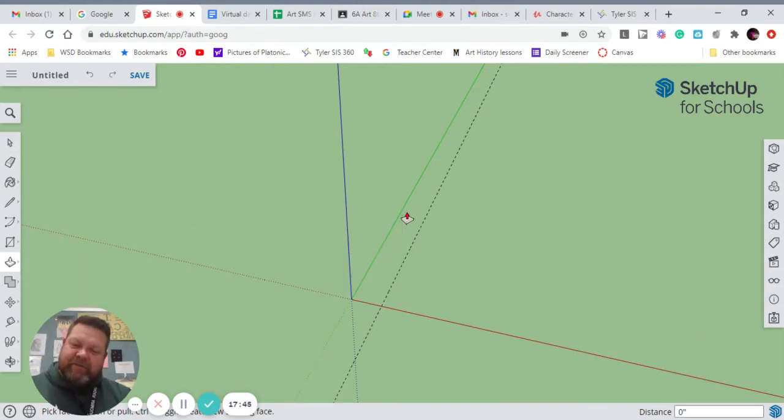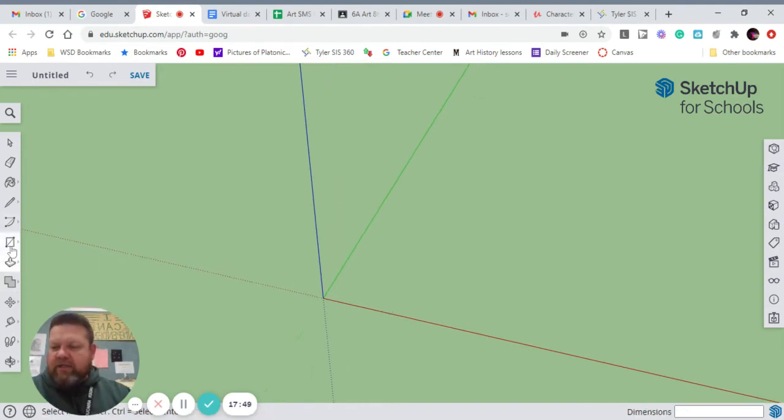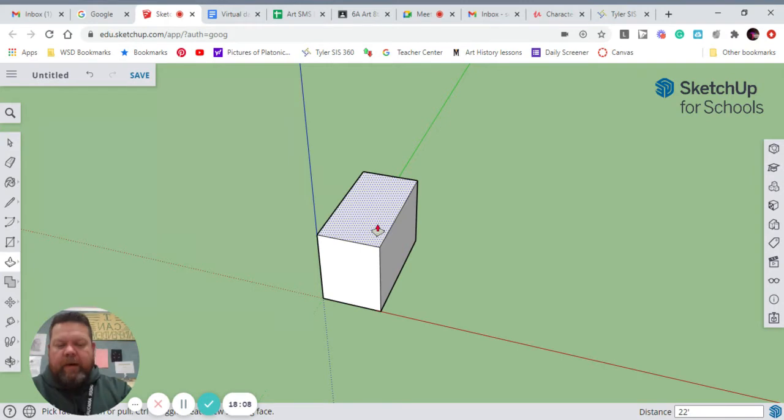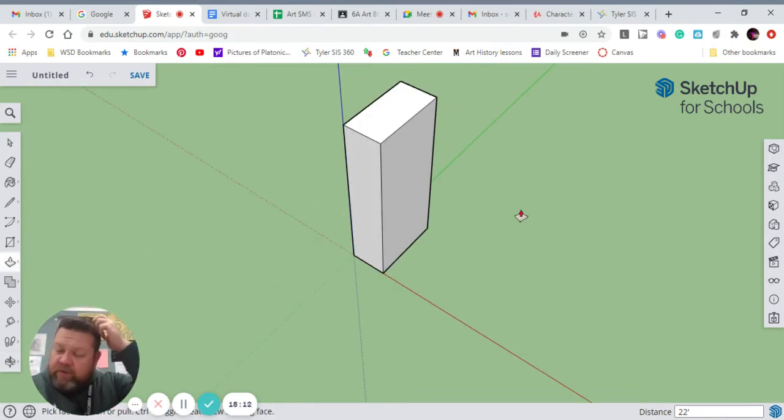Control Z, Control Z. Back to this. Or I can just drag out the box and I can hit 5 apostrophe, 5 feet, comma, 10 feet. Enter. Boom, 5 foot by 10 foot. It snaps to it. Now I can pull it up. 22 apostrophe, bam, 22 feet. Either way you want to do it, you can.